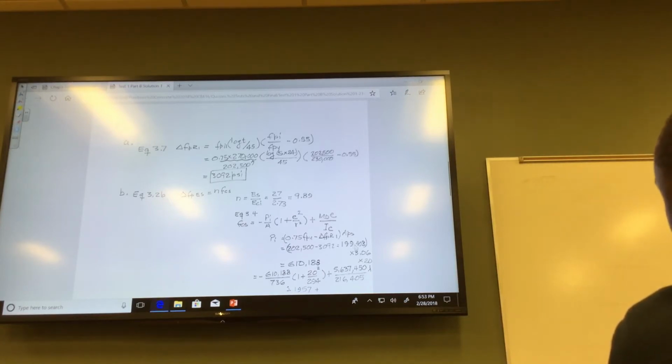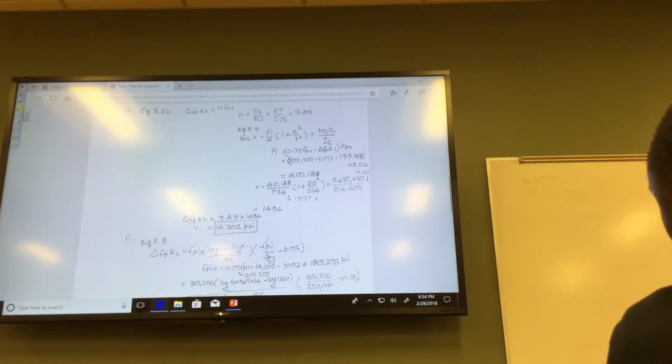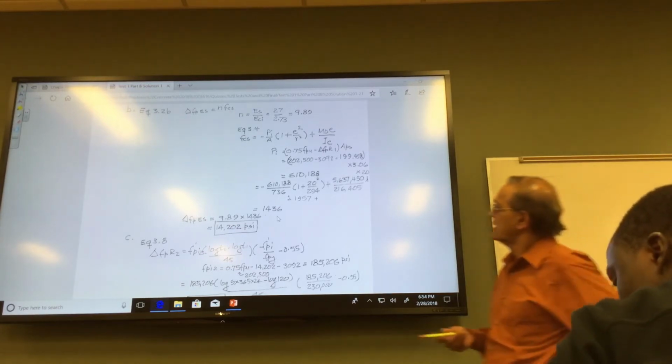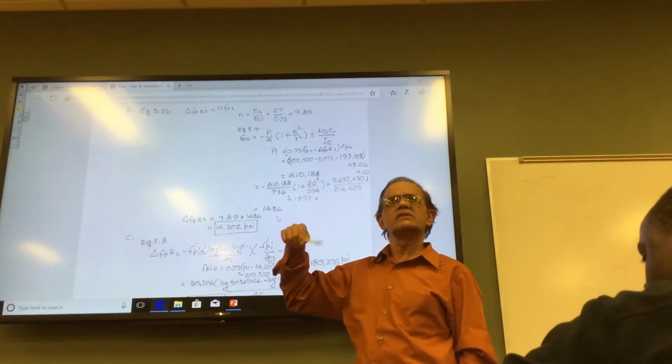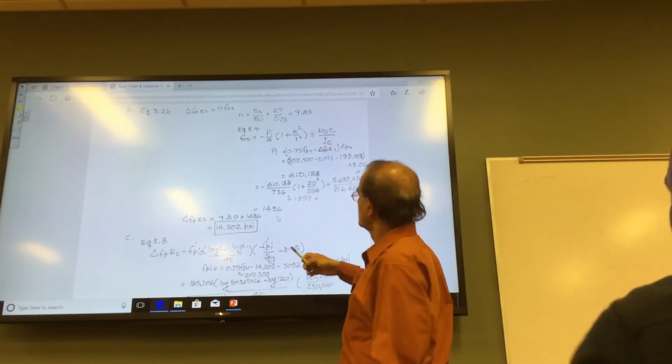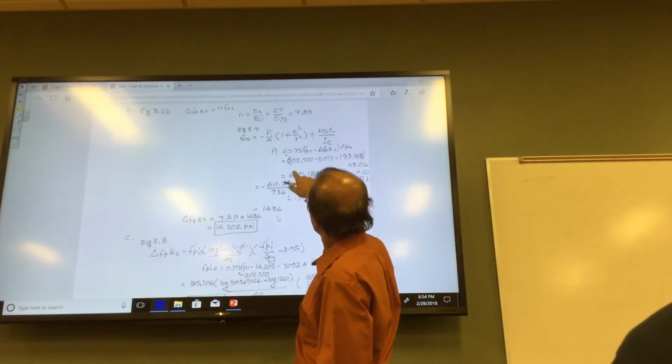So that you are at 199. And then the formula is, of course, N times the stress, where N is the ratio of E of steel versus ECI, E of concrete at the time of transfer, because the shortening is happening at the time of transfer. So that's the E you want to use. E changes, that's the whole point, so some of you used the final E. You want to make sure you use the E for that stage.